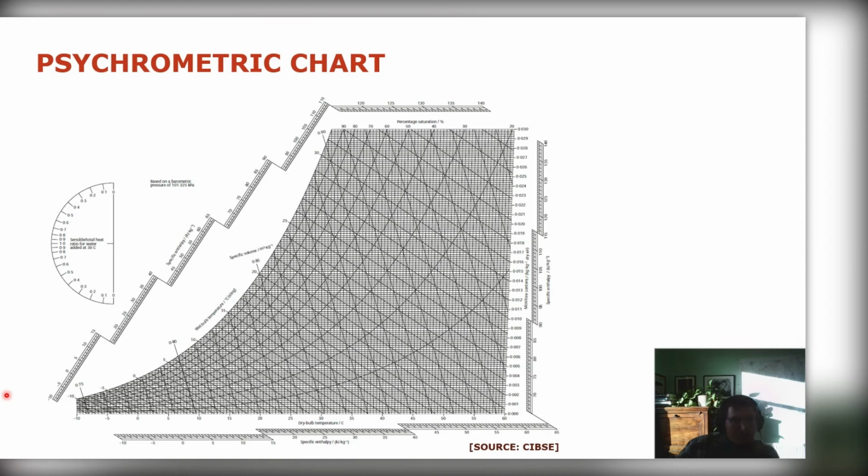Okay. When cooling, does the air reach its dew point? Yes, so it probably will. I would expect that it very likely can. Again, you could plot it on the chart. So if outside is, for example, 30 degrees and the relative humidity is quite high, then when you're cooling it, depending on the temperature of the earth itself, so let's say the earth is at 20 degrees, then yeah, if you come across, you'll see that you would start cooling down before you get to the temperature.